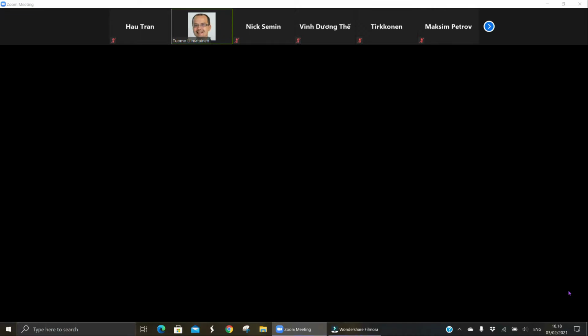Possible leaks, corrosion, because we have contacting surfaces, there is a fretting corrosion possibility. That is in some conditions something we need to consider, and fatigue always.